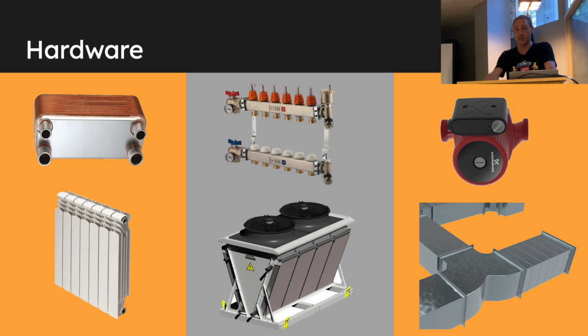So you have the machines, where the heat is extracted from the machines to the oil. But then you run that through a brazed plate heat exchanger, and then on your other end of the heat exchanger, you just plug in your hot water loop from your hydronic heating, your radiant heat in your house, or your hot tub, or your pool. So two of those ends just go into whatever water you want to heat. The other two ends go into your oil, a little bath for your miners.